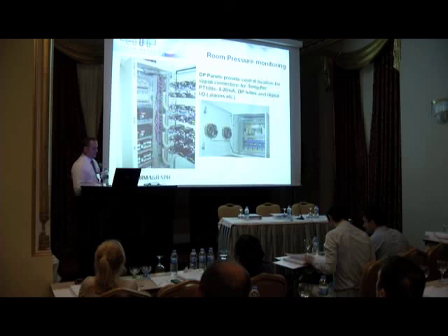So the reports offered include table of data, trends, reconciled alarms, audit logs, and importantly you get signature boxes at the bottom, where you can pick whether you want 1, 2, 3, 4, etc. And you've got optional batch reporting. All the data is 21 CFR Part 11 compliant when it's on the system. Once you export it to Excel, you need your visual systems to back up what the data is, because once it's in Excel, you can manipulate it how you like, which obviously your regulatory bodies don't like.